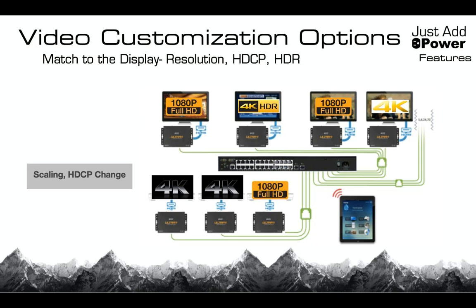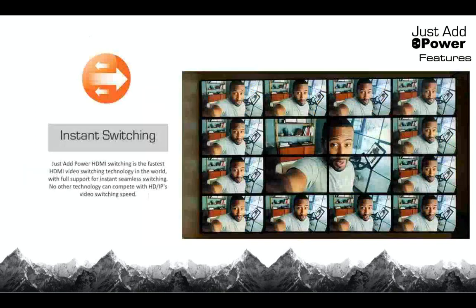Or the projector, whatever it is, has to renegotiate and re-handshake. The TV in the kitchen has to renegotiate and re-handshake. And when they both come back up again, we're watching 1080p everywhere. In our world, none of that happens. When the kitchen TV turns on, the theater TV never sees that action happen, so it doesn't blink out or anything like that. I'm going to send that 4K HDR content to every TV, and then at the kitchen TV, I'm going to change it to HDCP 1.4 at 1080p or 720p or whatever it needs, so that everybody gets the best signal, and everybody can watch all the same sources at whatever their bandwidth or capabilities require.